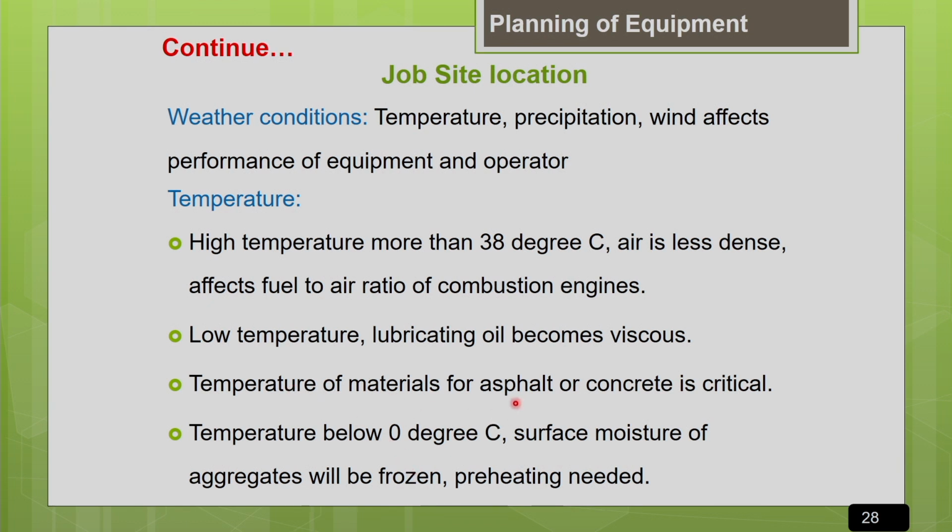Similarly, asphalt is a thermoplastic material. Obviously, its viscosity is totally dependent upon the temperature. In very cold weather, you can see that its viscosity will be significantly affected. You won't be able to work with the asphalt. So you have to maintain the working range of materials like asphalt or concrete by using some thermally insulated devices. You have to protect this material from the severe climatic conditions in places with aggressive climatic conditions.